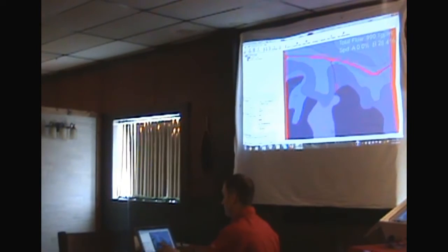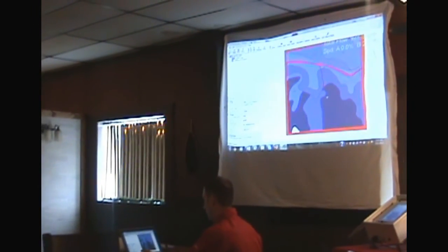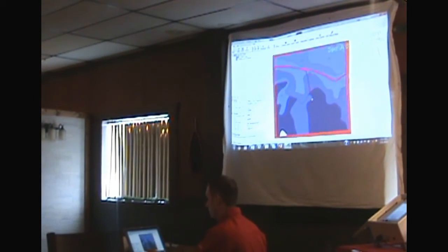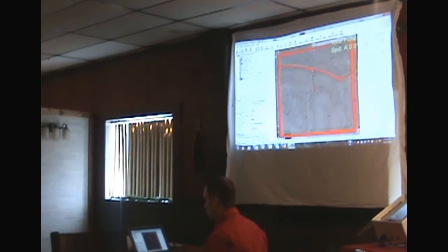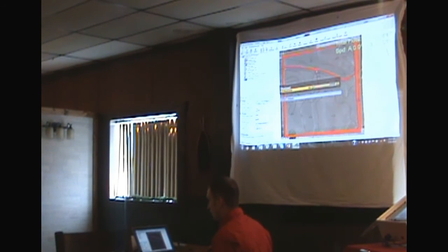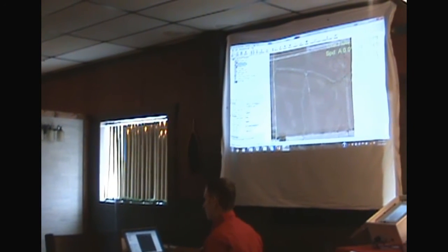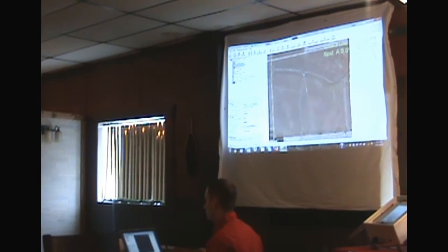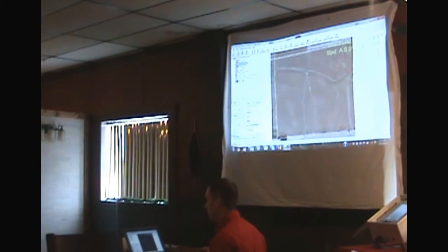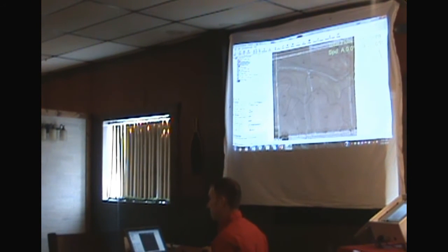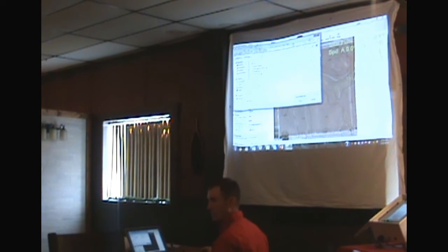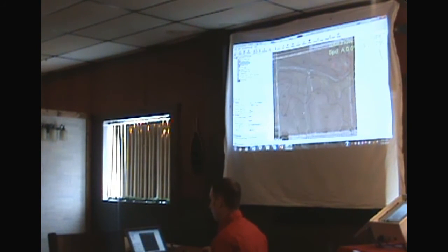Now the field map software. This is an actual corner. When you receive a new machine, it's going to look about like that. You essentially can either bring in a soils map, that's what this is, and it's as simple as going import and selecting that file, or you can create a new application layer in which you draw your polygons all over this map.